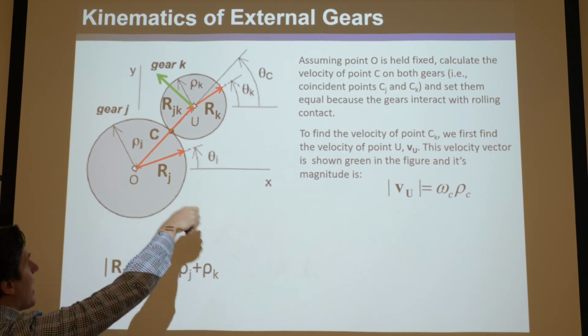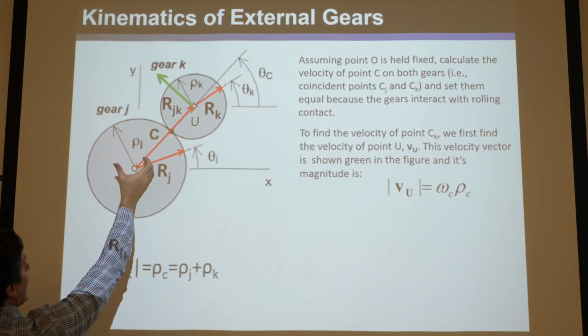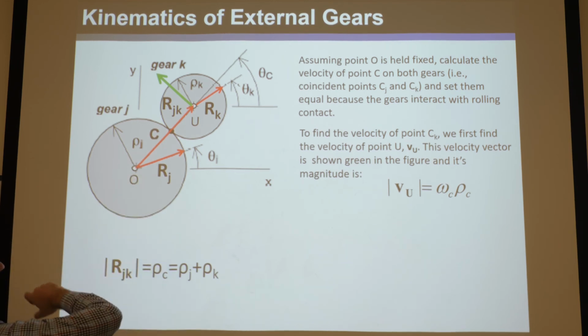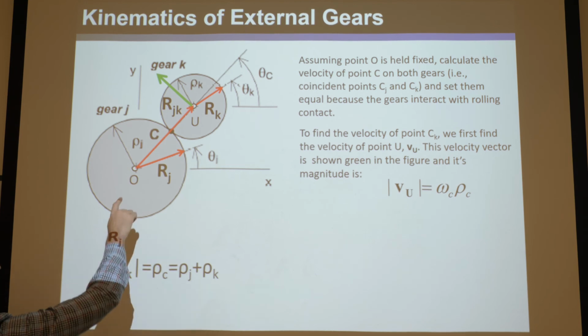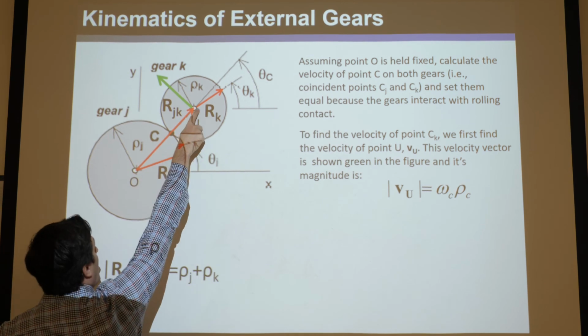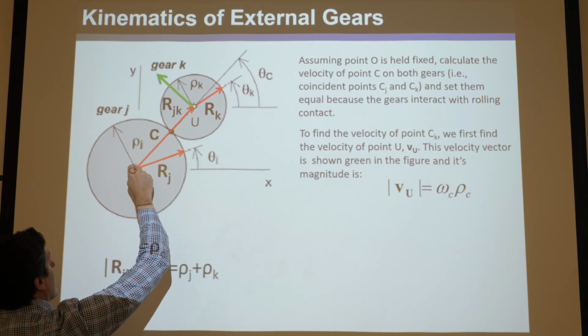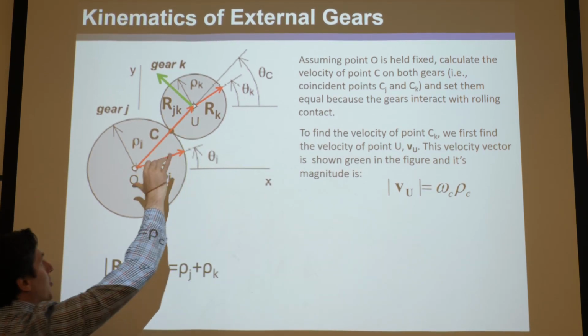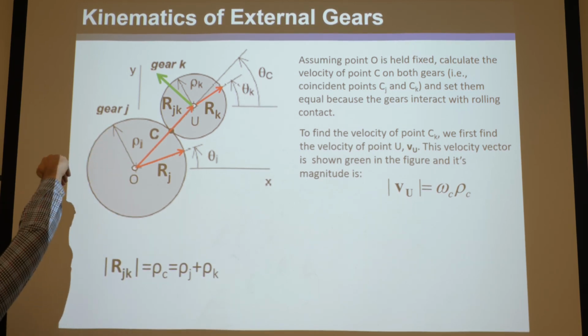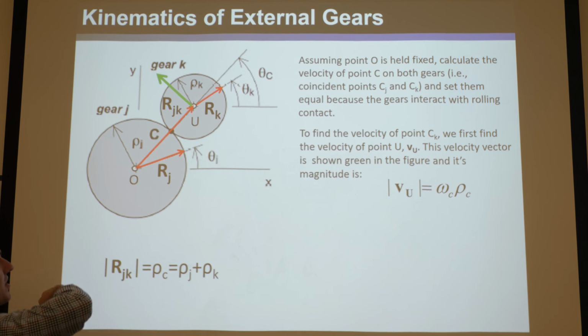And so now what we do is we take omega c actually, because we're imagining that fixed, and we're going from this bar to that point. So this point and this point are 2 points on the same bar that links those, and the angular velocity of that bar that is not drawn here, but I want you to visualize, is omega c.